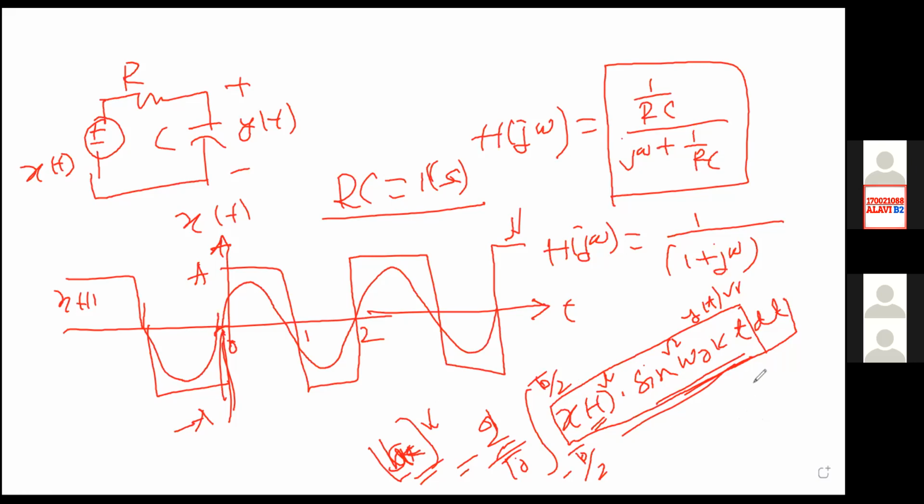It is very similar to the system that I described, okay? We are giving an input to a system with frequencies that are integer multiples of omega0 k, and we are checking whether an output is available or not. If that harmonic is present, you will get an output equal to the value of this integral. If no frequency is present there, that integral will be 0. In this way, you can extract which frequencies are present in your system.